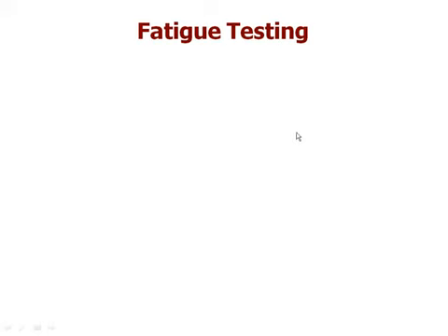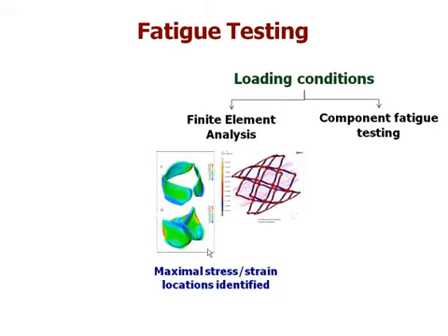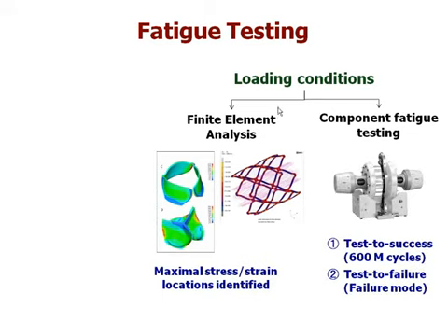So we now move to fatigue testing. And as we said, the loading conditions are important not only for the durability testing, but also fatigue testing. Once you understand these loading conditions, they are put into a finite element analysis model, a computer model. This allows us to understand where the maximal stress and strain on the device is. These loading conditions are also inputted in the component fatigue tester, and you then test the device to success at 600 million cycles, or you test the device to failure.